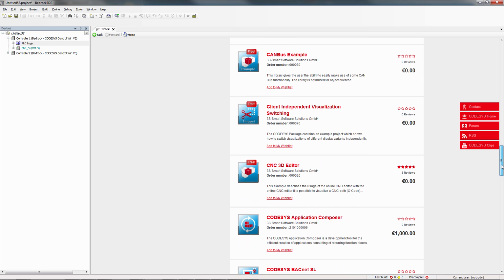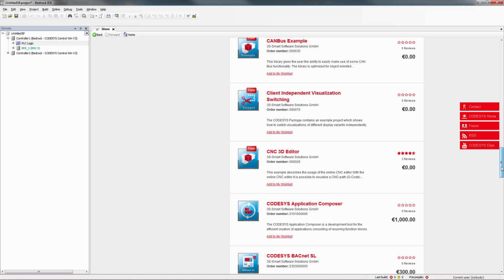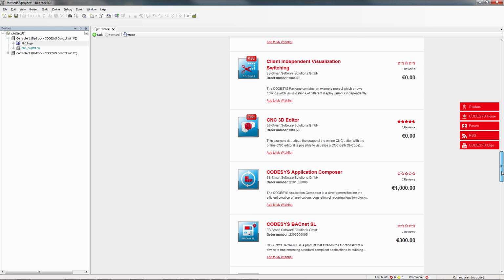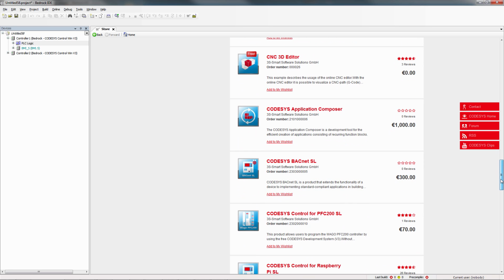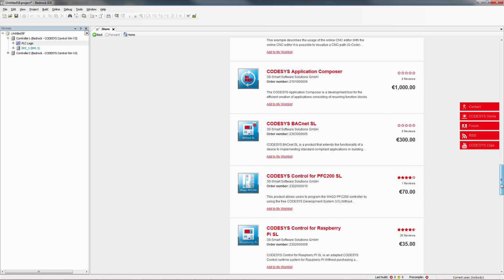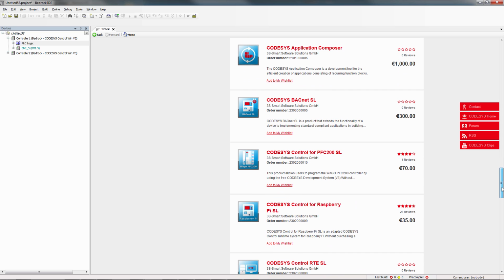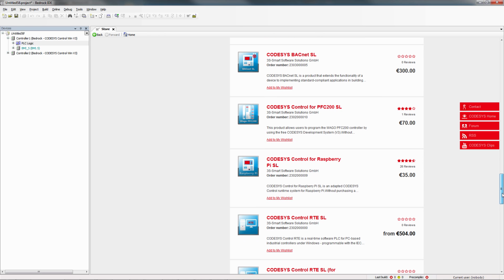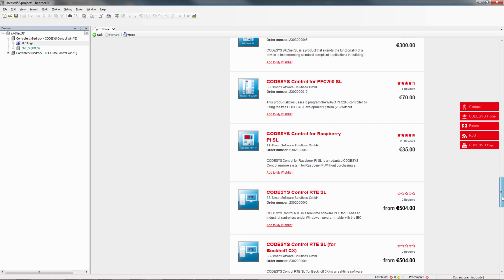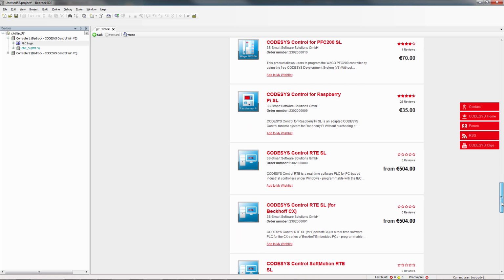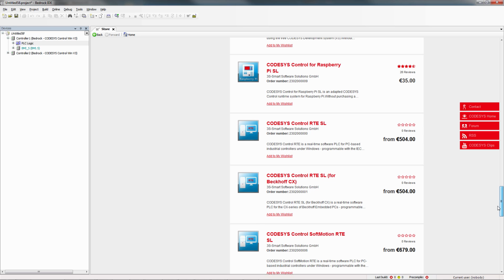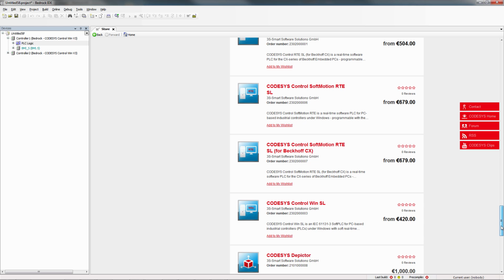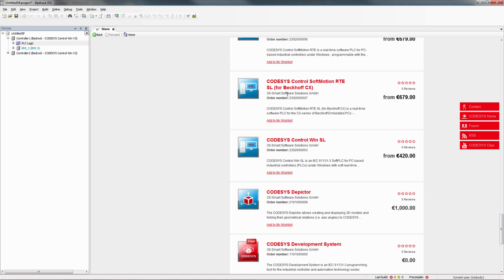And it has integration into ePlan. So if you use that for designing your plant, it'll automatically bring in all of the tags and such from your plant. It also has other items you can buy, such as the license for the control win. The one I'll show you shortly runs for 2 hours before timing out. You can extend that to indefinite if you want. And then it has quite a number of add-ons and examples for the CODESYS visualization tool. It's HMI that we'll talk more about later as well.